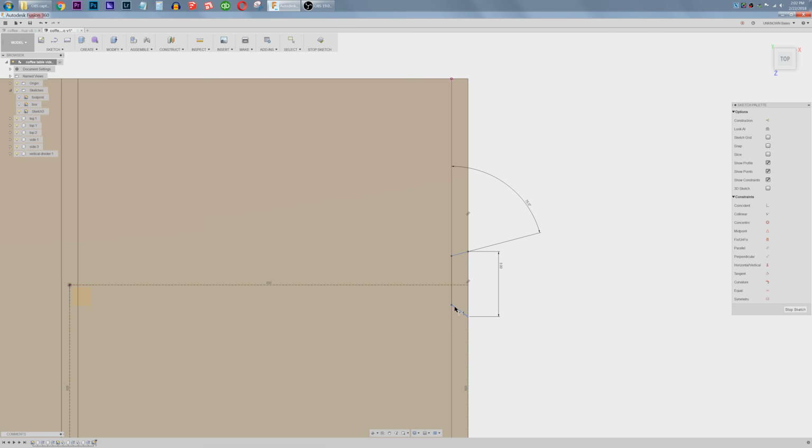Instead of typing this out as that same angle and all this, and centering everything amongst the center line, it's very easy to select this, hold shift, select this line, and after I have 2 lines selected that I want to be symmetrical, then I select the mirror line, and then click over here to symmetry. So there you go. When this angle is changed to meet this angle, and then they're also symmetrical amongst this line, they're perfectly the same distance. That means 3 inches is already established. 1.5 inches from here to here. Everything's black, everything's fully defined.